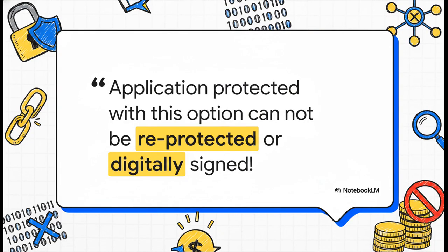But here's the crucial thing you have to remember. This is a final step. You only turn this on after you've done everything else, like digitally signing your code. If you do it too early, you're going to lock yourself out from making any more changes. So save this one for last.